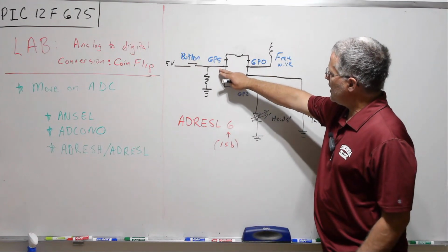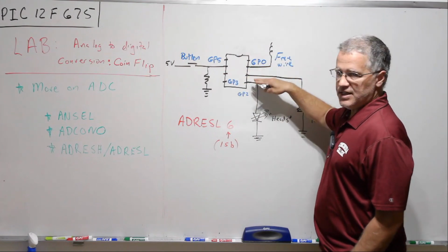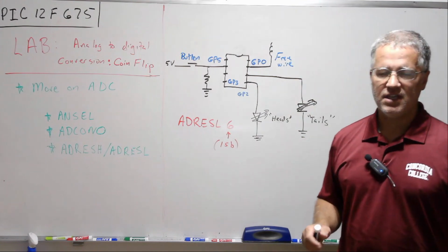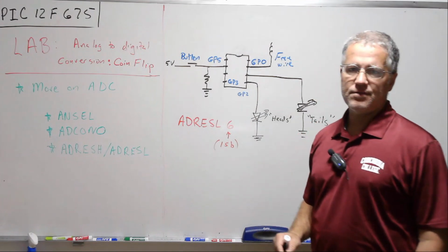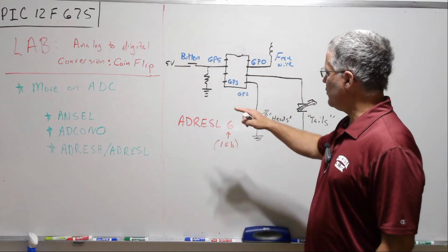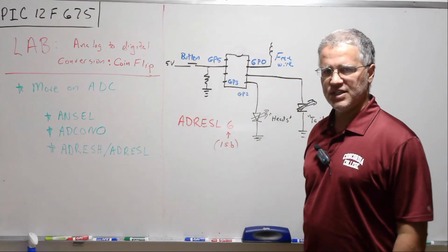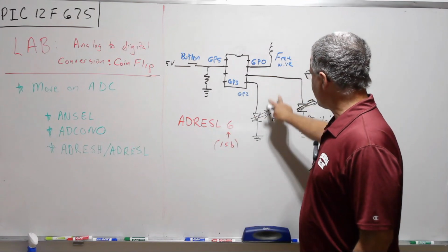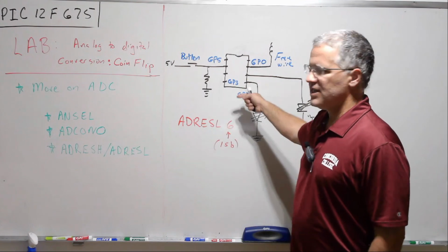We're going to have pin 0 as our analog in. The rest are going to be digital, and we're going to use pin 5 as the input pin, and that will be relayed on a button press. So when we press a button, we will launch the analog to digital converter, pull the signal, and then represent either heads or tails with two outputs here.